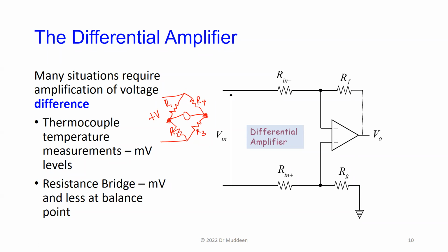The thing with this is that if you notice, this point here is carrying a voltage. Let's say the bridge is being powered by 15 volts, and let's say all of the resistances are equal, just for making an assumption. If all are equal, it means that these 2 points are at 7.5 volts.